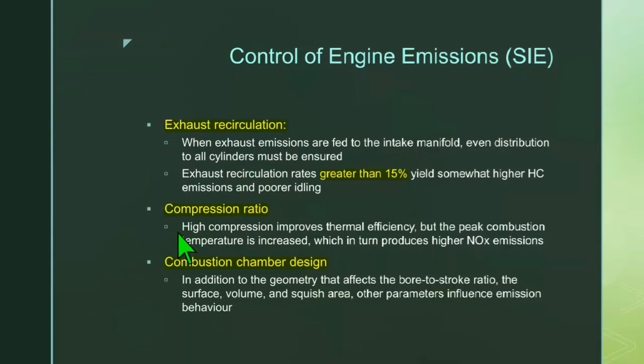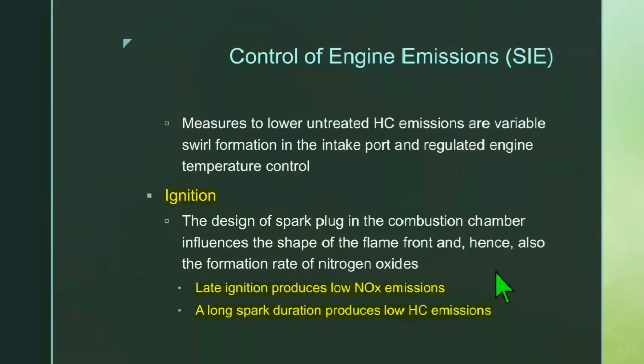Compression ratio. High compression improves thermal efficiency, but the peak combustion temperature is increased, which in turn produces higher NOx emissions. Combustion chamber design. In addition to the geometry that affects the bore-to-stroke ratio, the surface, volume, and squash area, other parameters influence emission behavior. Measures to lower untreated hydrocarbon emissions are variable swirl formation in the intake port and regulated engine temperature control.